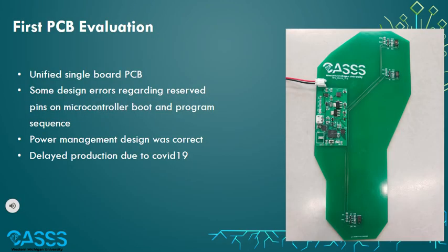Our first PCB design is shown. With this design, it is apparent that it's meant to collect data from the foot. It is an entirely unified board with the main microcontroller area and the PPG sensors. One disadvantage of the design is that the flat surface may not be optimal for the sensors, since the foot is a curved surface. Plus, it may be uncomfortable for the user to wear.